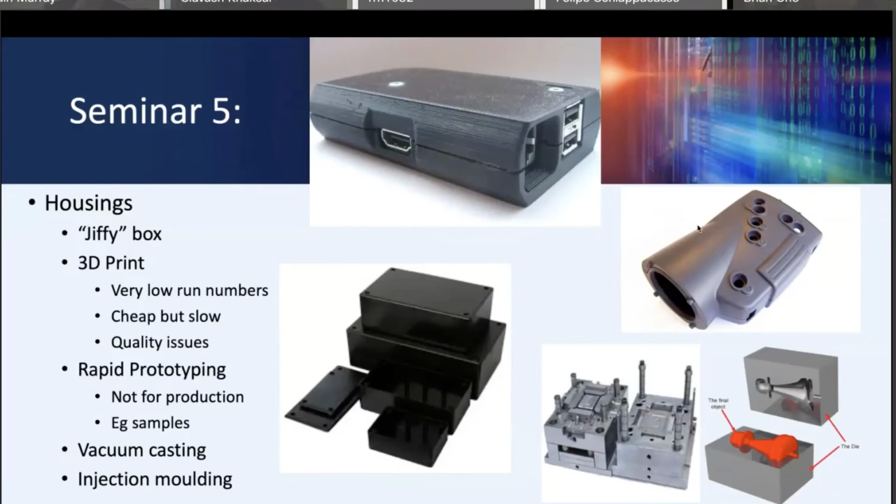It has to have a mold made for it so that when you heat the plastic, you pull it down over the mold and you force it to fit by vacuuming the soft plastic over the mold. So these are quite cheap, can be quite robust, but they're not generally used for large production runs.